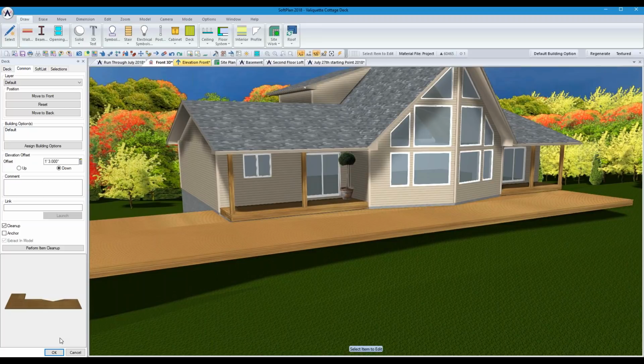Now relative to the main floor where we've drawn this, the bottom of this deck is 15 inches down. So it's 15 inches, then we add 9.5-inch joists and 1.25-inch decking. So the top of this deck is about 4.25 inches down from zero, which is the top of the foundation here. So you can see about a 4.25-inch gap that we can still see foundation before we get to where the sill plate would sit to move up from there on the main floor.